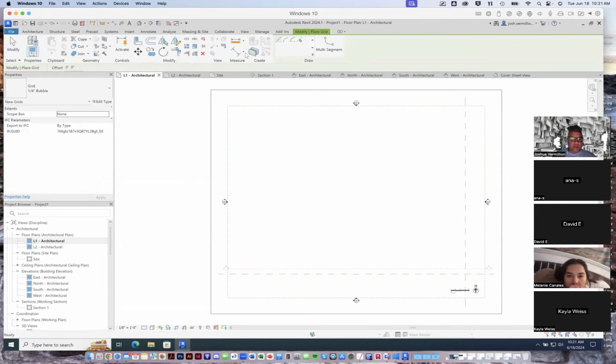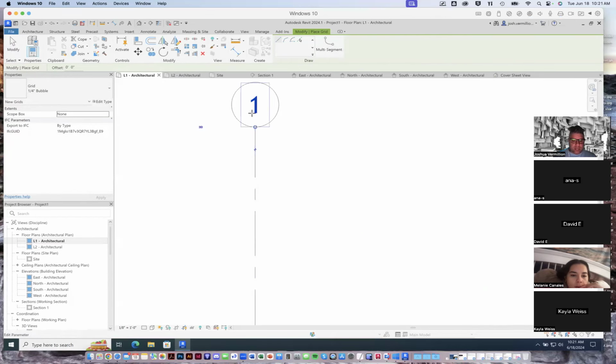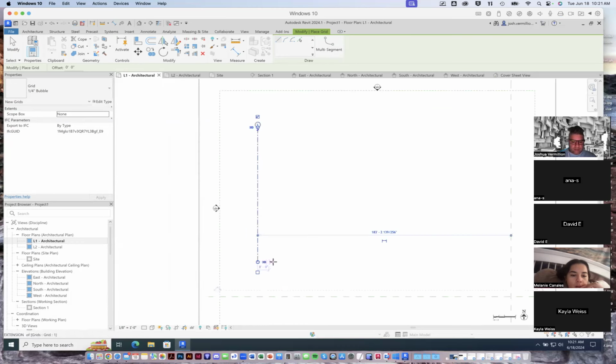So what I'm going to do is just click grid. You'll see that this thing changes, and now we can start to draw grid lines. Okay. You'll see that each line is then labeled. So as I start to draw these, the first one's labeled 1. Now if I move over, I'm just sort of moving my mouse around, I'm not really clicking or anything. You can see that it's going to IntelliSense. Maybe I want to line this up with the previous column line that I drew, and then it'll start to dimension things. And it's trying to find some nice round whole numbers to use. So in this case, I just said I want 6 24-foot modules. So now I'm going to click, and I'm just going to move up and make another one. I'm just going to move over here.